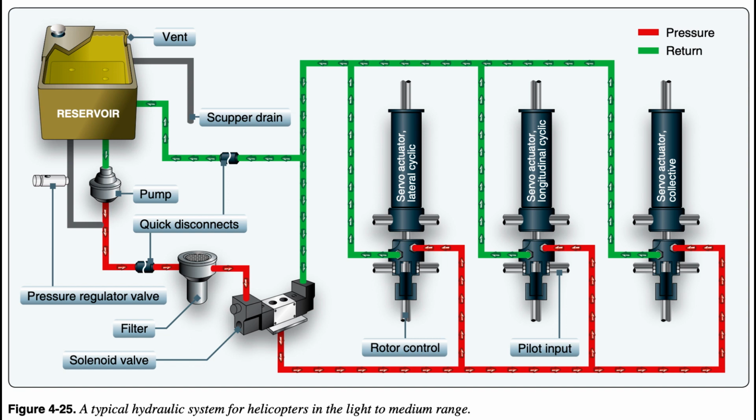When making a control input, the servo is activated and provides an assisting force to move the respective flight control, thus reducing the force the pilot must provide. These boosted flight controls ease pilot workload and fatigue.